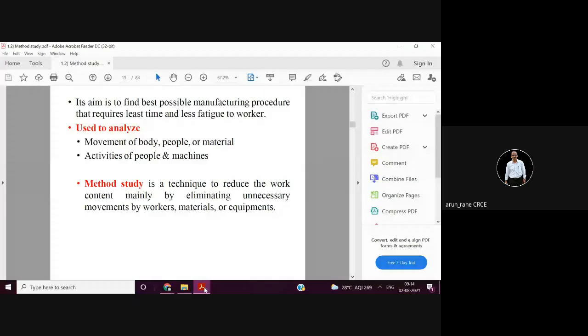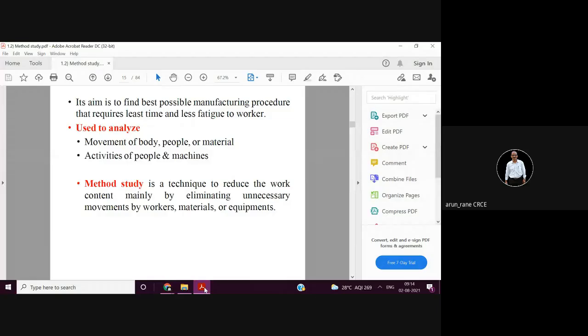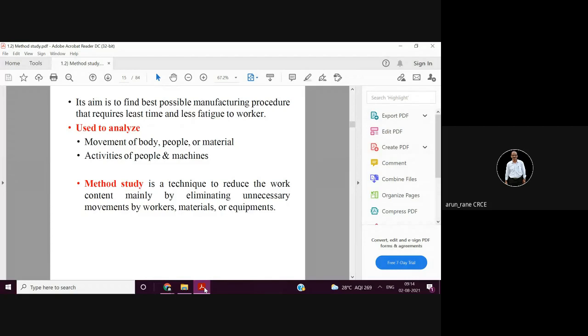If you have not understood this example, I will give another example. Suppose you have three machines: lathe machine, milling machine, and drilling machine. In the lathe machine, the time required is 3 minutes. In the milling machine, the time required is 5 minutes, and in the drilling machine, the time required is 1 minute. Now, which is the bottleneck? Milling machine, and you want a cycle time of 3 minutes. The lathe machine is able to produce every 3 minutes. The drilling machine is able to produce in 1 minute.